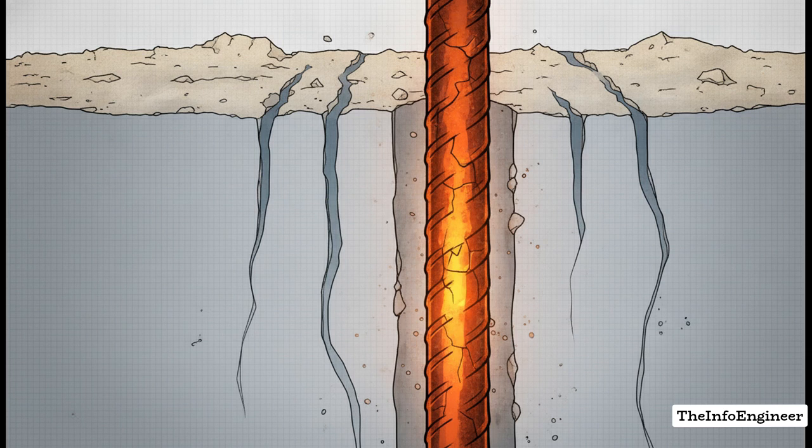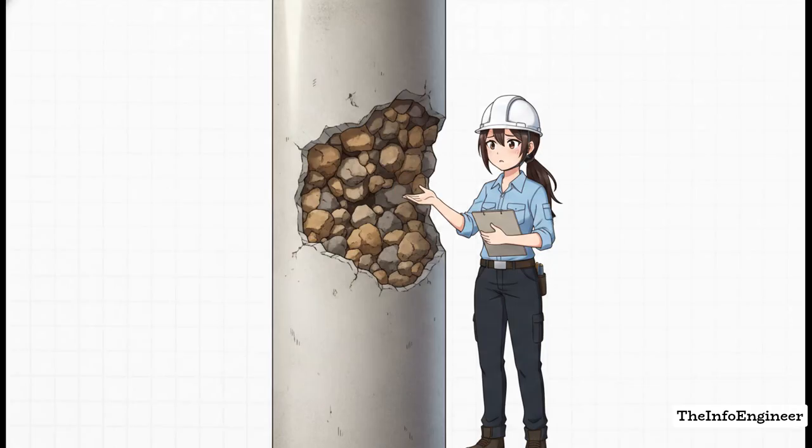Worse, as the water pushes upward, it carves out continuous, permanent capillary channels. This permanently spikes the permeability of your hardened concrete, practically inviting water and chlorides right in, which leads directly to rebar corrosion. Plus, that excess water pooling under your rebar physically breaks the critical bond between the steel and the cement paste. And then there's the most visible consequence, honeycombing.